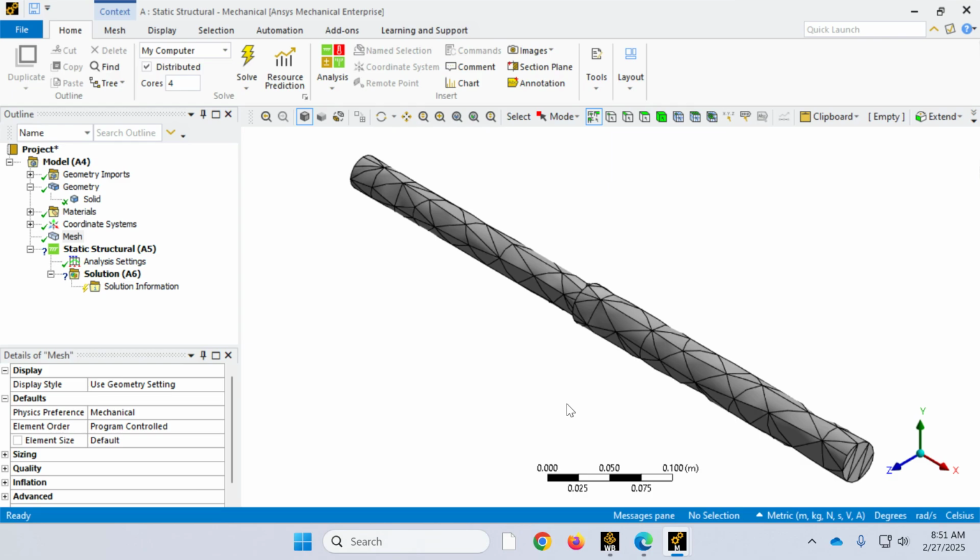Not really. The reason we lost that is the size of the element. Relative to the size of my part, this is a coarse mesh. I can continue to use it, but then I'm going to get a distorted behavior because it no longer looks like a cylinder. So before I move any further, I want to refine my mesh.